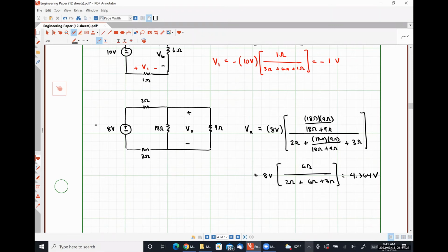And I'm just thinking of, on a test, working a problem. If you only have a single voltage source with several resistors and all that kind of stuff, and you can fairly easily do resistor combination techniques, I would argue that voltage division is probably a pretty straightforward way to go. But if there's multiple voltage sources, voltage division is probably not your tool of choice. Unless the two voltage sources were connected in series to where you could make a simple combination or something like that. But if you got a voltage source on one side of the circuit, another voltage source on another side of the circuit, leave that alone and use something else. All right.